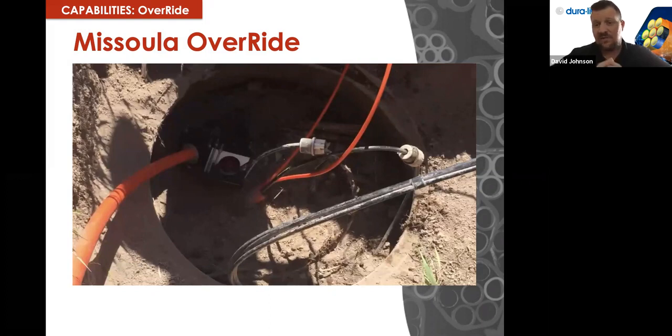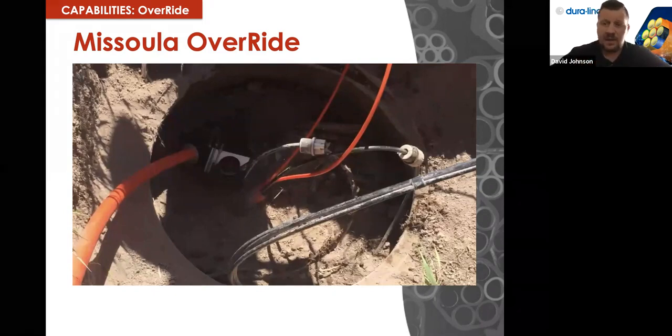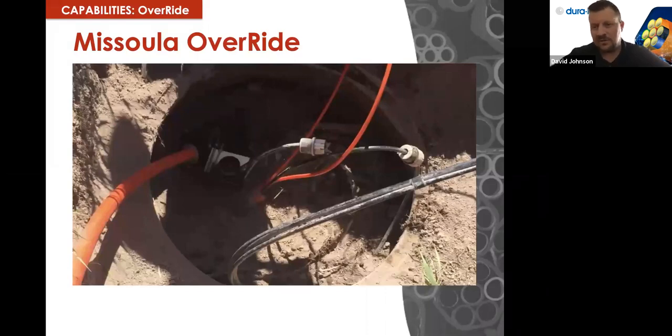Once we have that, we have a calculator where we put in two or three microducts and calculate up to a 55% overall fill ratio of that duct. That's what helps us calculate it. It's not a calculator we've promoted out to customers, but we support you. We just ask that we find out what the ID is and the OD of the existing fiber, and then we can tell you exactly how many microducts you can place inside.